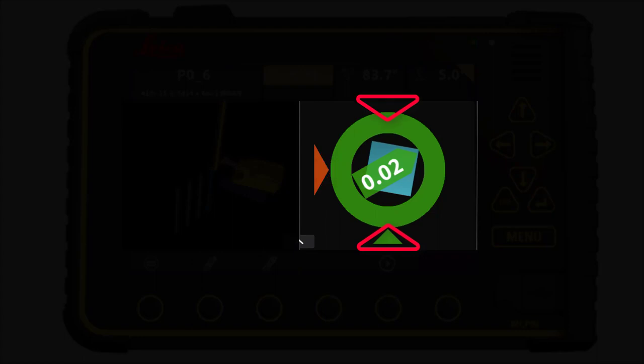The upper and lower arrows show the hinge angle. The left and right arrows show the tilt angle. Note, right now the arrow is red and thereby showing the tool out of tolerance. The tower needs to be tilted towards right to have the correct angle before piling. Once the arrows are green, the angles are within tolerances.